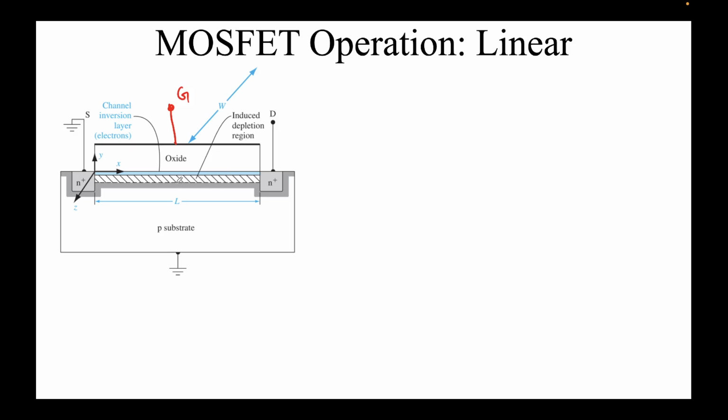So this blue region that you see is the inversion layer, which will be of electrons, since this is a p-type substrate. The dashed region that you see is the depletion region, due to the fact that we are applying some potential. What potential? You can clearly see if the inversion is there, you have to apply a positive bias. Some assumptions: because this inversion has already formed, we'll be operating at Vg greater than Vt.